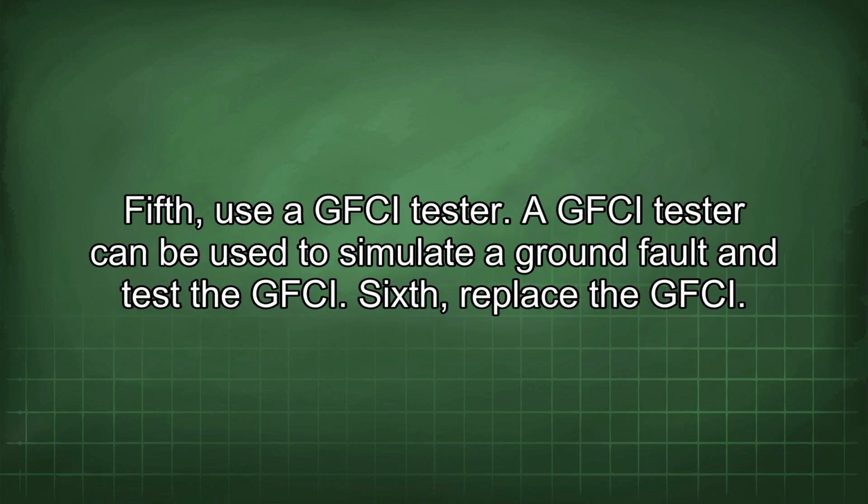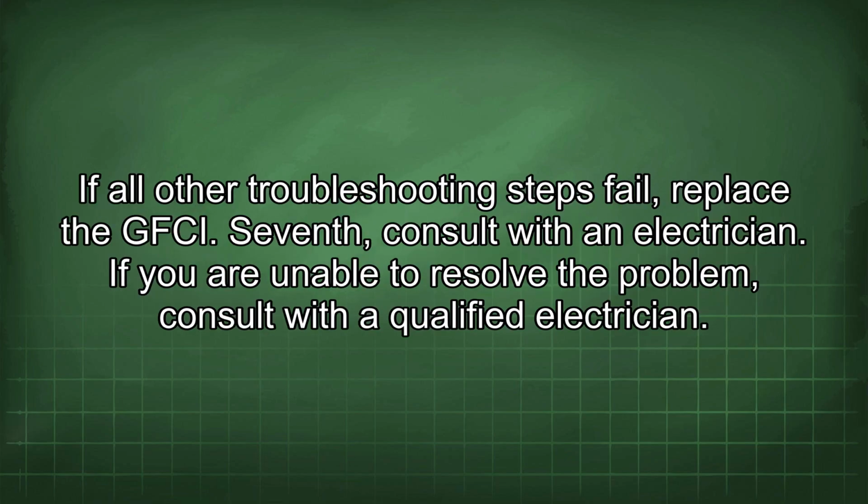Fifth, use a GFCI tester. A GFCI tester can be used to simulate a ground fault and test the GFCI. Sixth, replace the GFCI. If all other troubleshooting steps fail, replace the GFCI. Seventh, consult with an electrician. If you are unable to resolve the problem, consult with a qualified electrician.